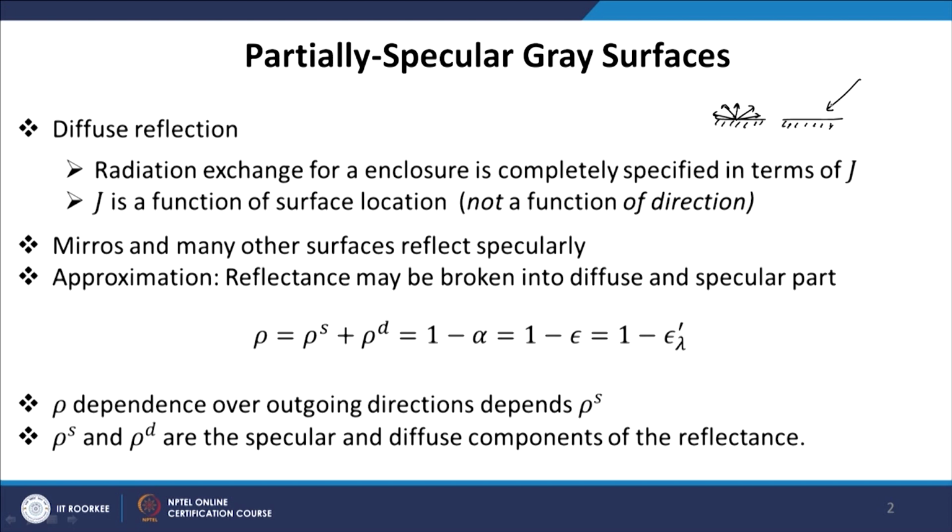receives some radiation. It may be coming from a single direction or it may be diffuse also, but the reflected radiation is diffuse. So, we have a diffuse emitter and diffuse reflection, and the combined can be diffuse also. So, we do not have to distinguish what is emitted and what is reflected, we call it radiosity. That was a powerful